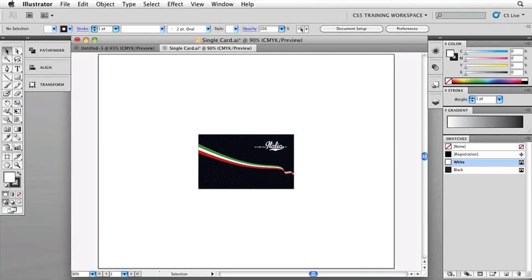So how do we change the actual size of the artboard itself? Well, like I said, there are a few ways to do it, and really the most important thing is the artboards tool. Now, I pointed this out briefly earlier on. You can see it's over here in the tools palette. And if I hover over that, you can see it has a simple keyboard shortcut, Shift and O. So that's definitely one you want to remember because we're going to use it a lot moving forward from here.